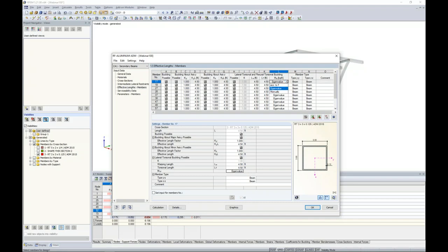Now, the critical buckling moment can be determined by default with an eigenvalue analysis. So this is a much more theoretical approach where we are essentially going to consider 4 degrees of freedom on either side of the beam member. Now, our assumptions with this is that the member is laterally and torsionally restrained at the ends, but free to warp. So if these are your constraints and you want to run it according to an eigenvalue analysis to determine the critical buckling moment, you can leave this as default.